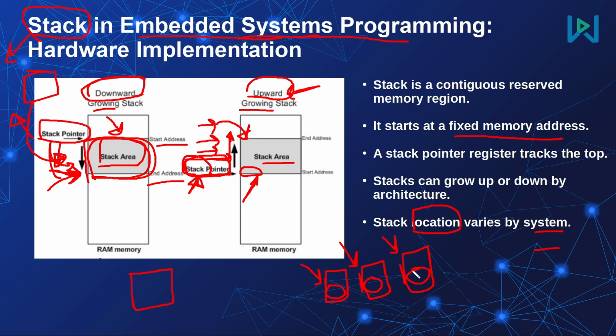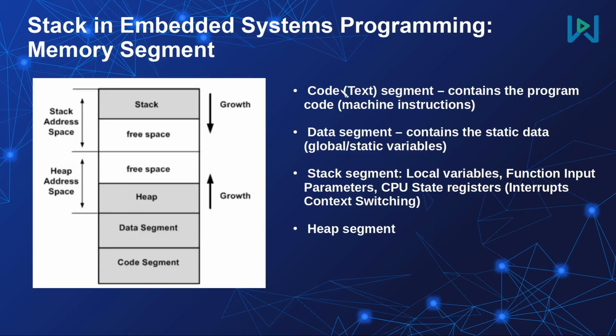It is just a matter of programming the start address of the stack, and this will be done by updating the stack pointer of the CPU. From a low-level embedded system programming point of view, the program or the binary will consist of a set of memory segments needed to maintain a proper execution flow of our program.